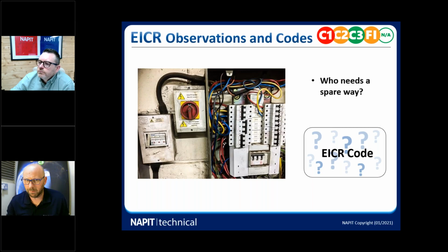We've got a very short submain cable that's got no protection. It's just fed straight off of what the incoming supply is fused at. So we may need to look at that, and there's a fair bit going on there. This is a kind of dangerous situation that we see from time to time. It usually happens in these types of workshops, car mechanic type of thing. Somebody needs an extra feed for something. They've got a little bit of knowledge, but not a great deal, and we end up with a situation as what we can see on the screen here.